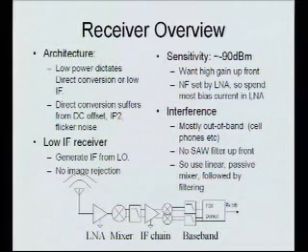And as long as you design your IF chain so it can handle different IFs, which is actually not that hard at a low IF, then you can also just change your IF, and so step not only which side your image is on, but what its offset is. Would you also change your LO with respect to that? Yes, you would. So you couldn't do it on the fly. You'd have to do it from different received packets. You have to just recenter yourself.